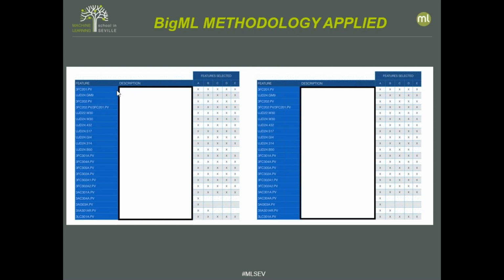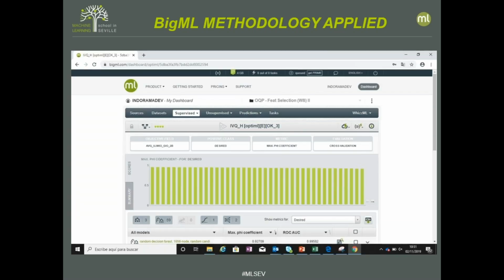Here we can see variables such as the throughput of the process, the concentration of the catalyst, water, oxygen, the ratio of air compared to the feed to the reactors, intensity of agitation, and level of the reaction, which at the end has impact on the residence time of the reaction and its efficiency. So all these are the ones that were evaluated in this sense.